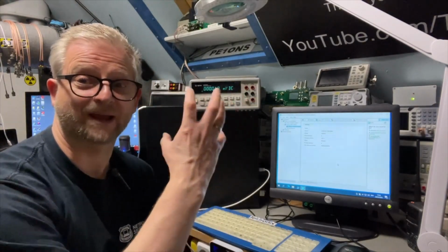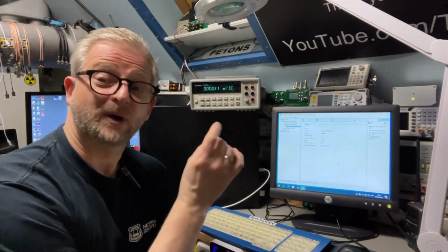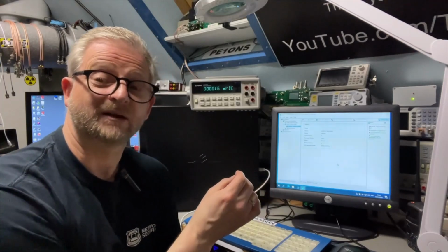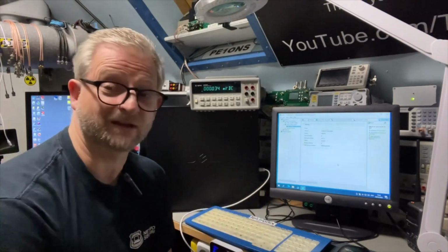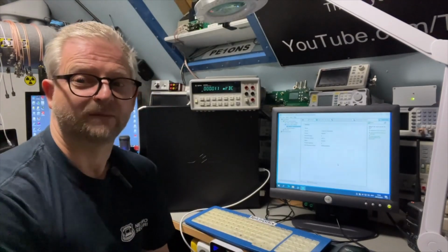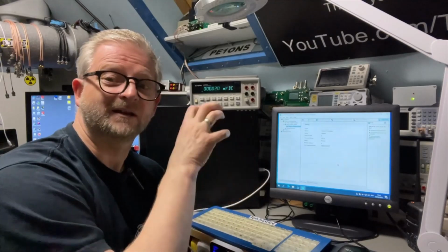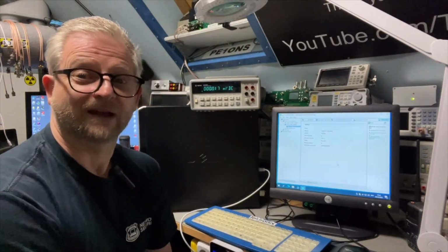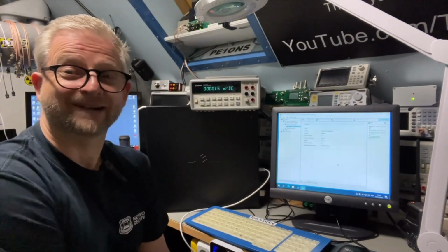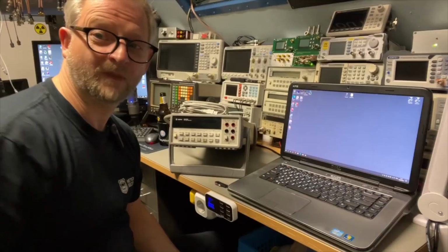That's also one big package I will show you. And then it will detect automatically, wait, there is already a VISA available. Do you want a Keysight VISA as a secondary? And you just say yes, do it secondary, because most applications prefer the National Instruments VISA. So that's what I read. Let's see how that works in practice.